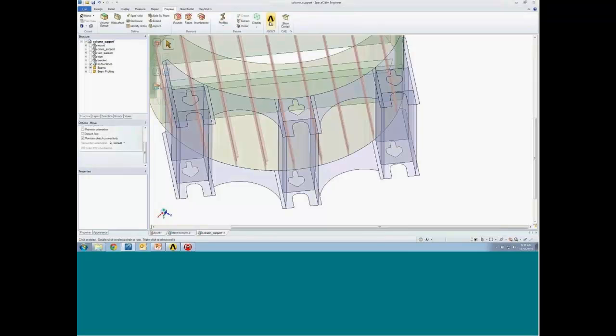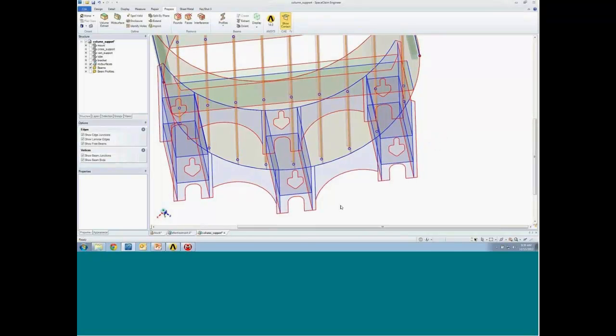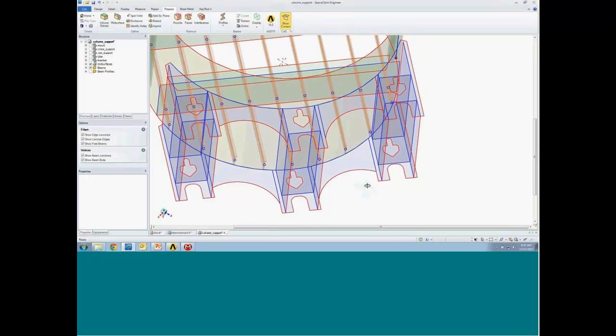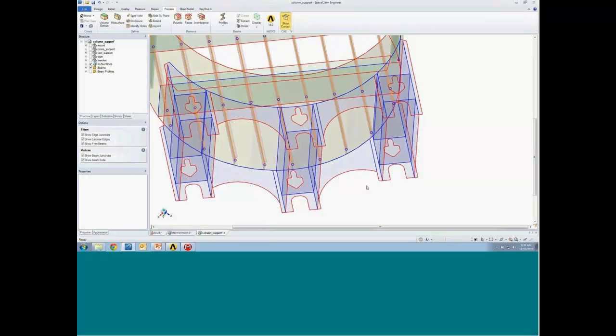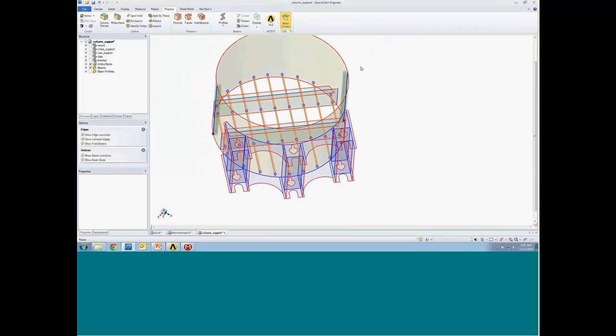Now when I run that show contact option, hopefully you can see the edges along the bulk of the perimeter, the 3 edges of each of those faces is now blue. And you have the solo edge sitting out front. So this can really give you a great visual indication of if you have all your contact points and your nodes lined up properly.